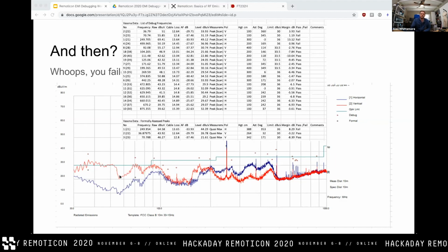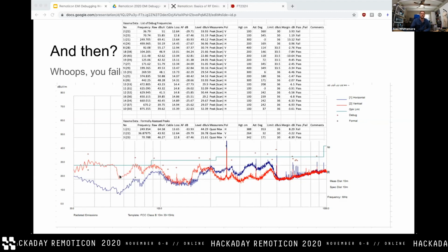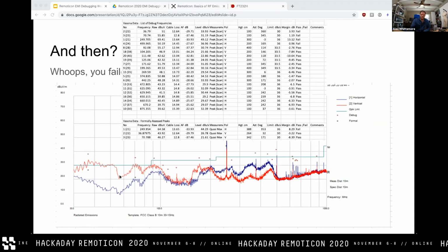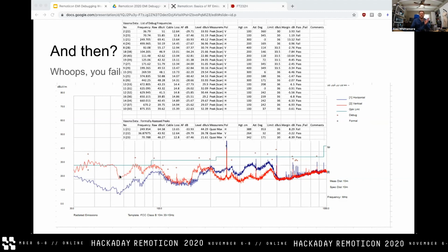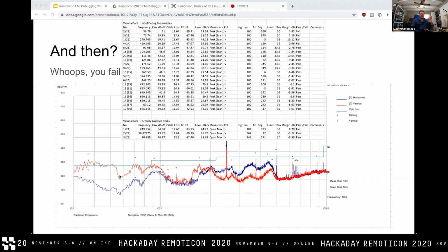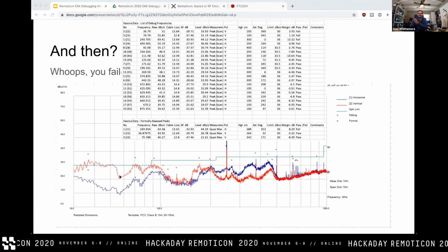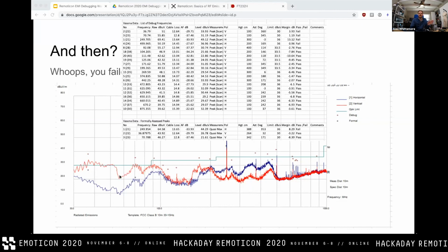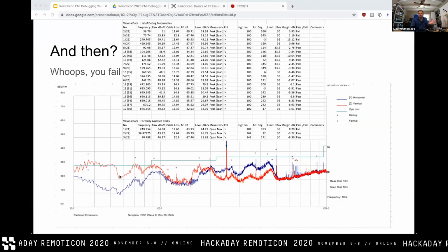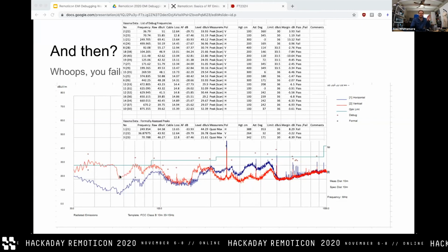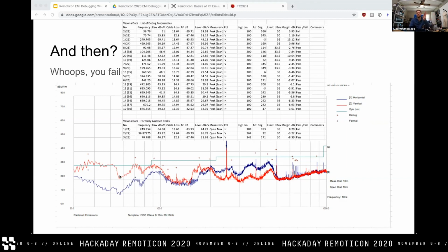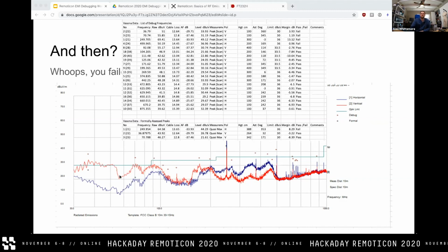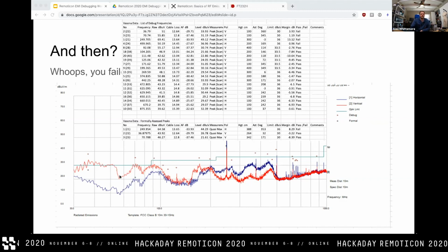For time immemorial, the only practical way to do this is basically make a device that measures the received power at a specific frequency, and then just tune that specific frequency through time, ideally as quickly as you can, but listening to this frequency, then move to the next frequency and listen, then move to the next frequency and listen, and so on. That's swept spectrum analysis.